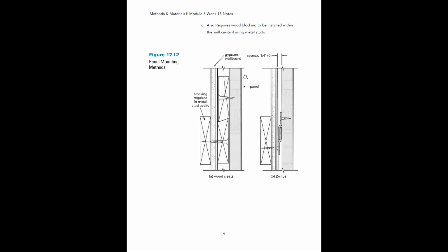So here's what those look like in a section view. Here on the right side is our actual flush wood panel. Now here's the cleat method. So you're screwing this piece of wood, this is the cleat, into the back side of the panel. You then have another wood cleat that is going to be screwed into the wall into some sort of wooden blocking that is within the wall structure. After you have everything screwed together, you're basically taking the panel with the cleat attached to it and hoisting it into place and resting one cleat on top of the other cleat.